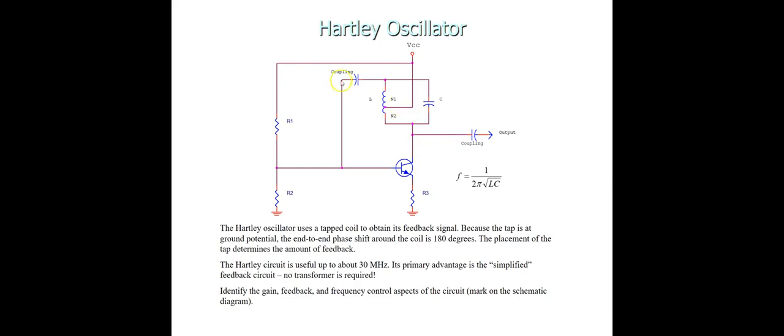The inductor in this Hartley is L1, and in the DC analysis this L1 will be shorted, and the collector of Q1 will be connected to the positive VCC. So you see here in the DC analysis VCC will be connected, and this will be powered from here and then to here.